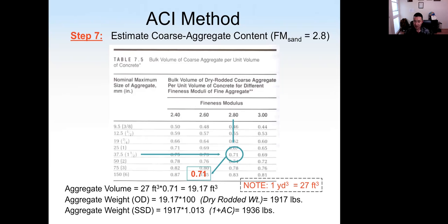So this is dried coarse aggregate. Now when we design our concrete for sand and coarse aggregate, we need to give saturated surface dry condition. Why do we need SSD? Because only under SSD condition, the aggregate will neither absorb moisture from nor give out moisture to the cement paste. Otherwise, the water cement ratio will change.